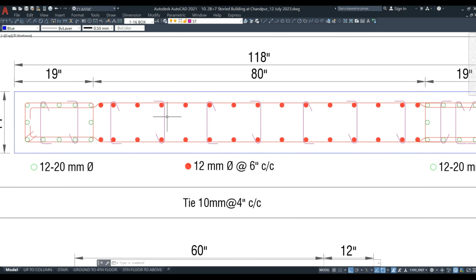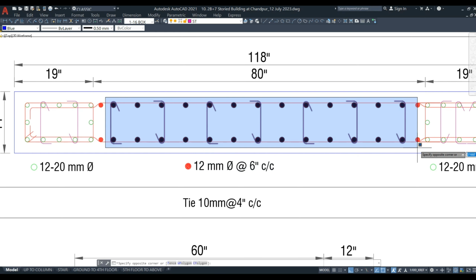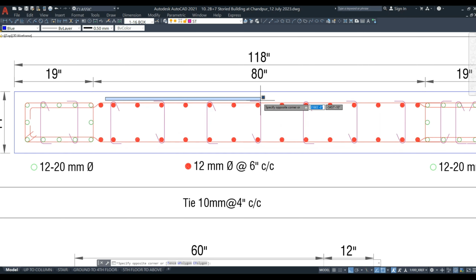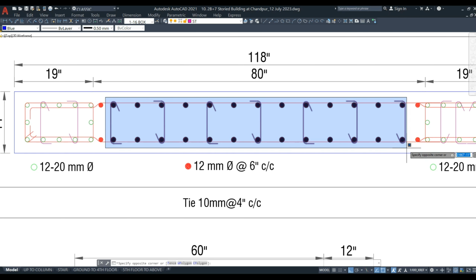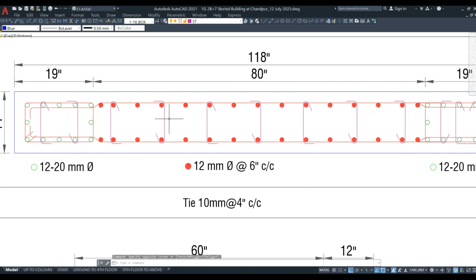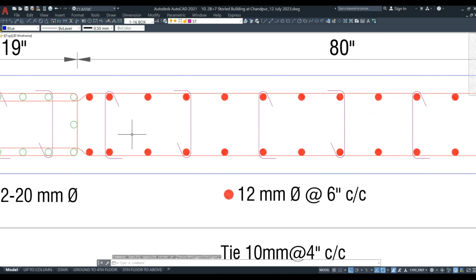But I would suggest not to exceed 14 inches. However, you can do away or even not use any tie here, but I would suggest using ties here, transverse reinforcement here, so that you can use this reinforcement in your special or seismic wall as well. And use 14 inches maximum spacing, but try to use lower than that.